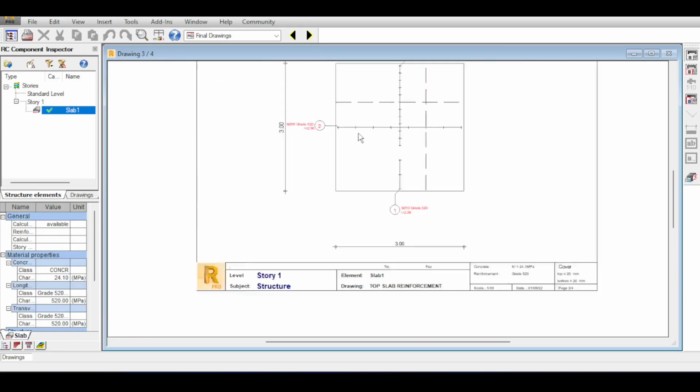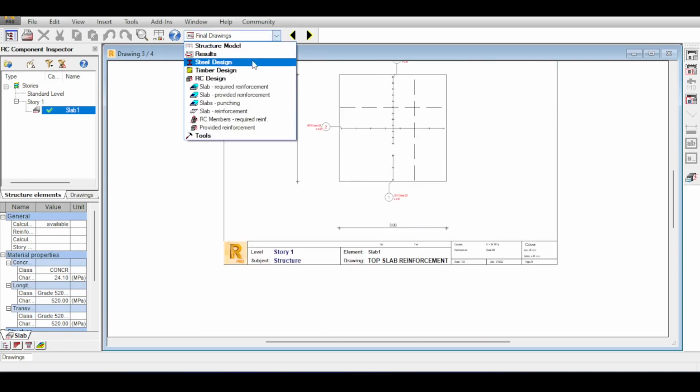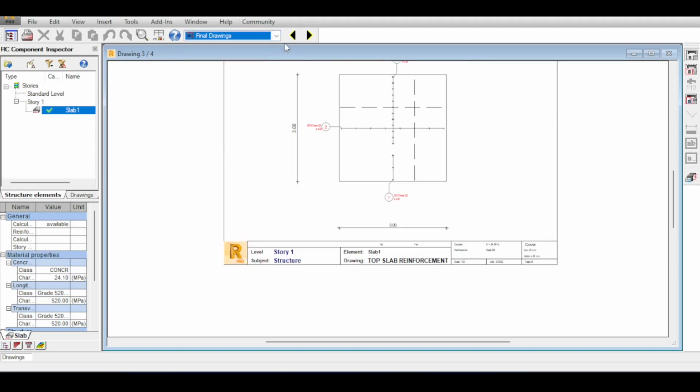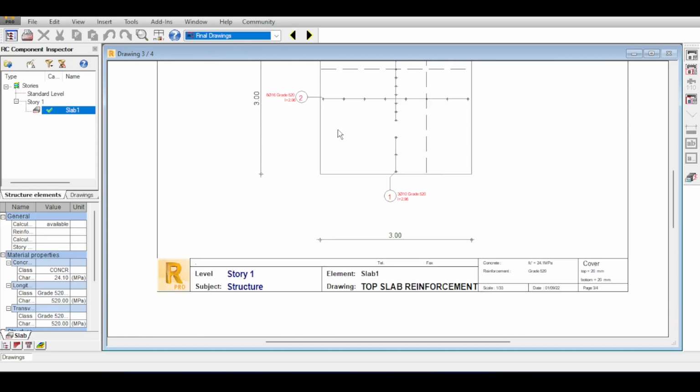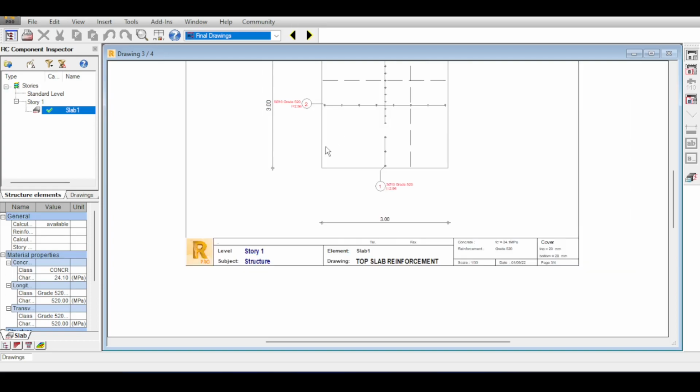It's really low, and the reason why I don't like that, and this is a small hint for you, is because the spacing between the reinforcing bars is too large, and this will be a problem when you have to control cracks, because usually there are maximum distances recommended for the spacing of bars. It's not recommended to have huge concrete distances without any reinforcing bar. So my suggestion to you is to decrease the diameter and let Robot run the analysis again to find the adequate design of that wall. I'll just show you how it's very quickly done.